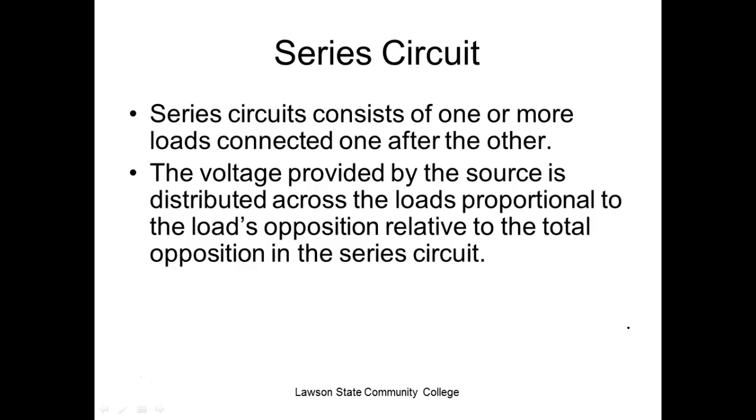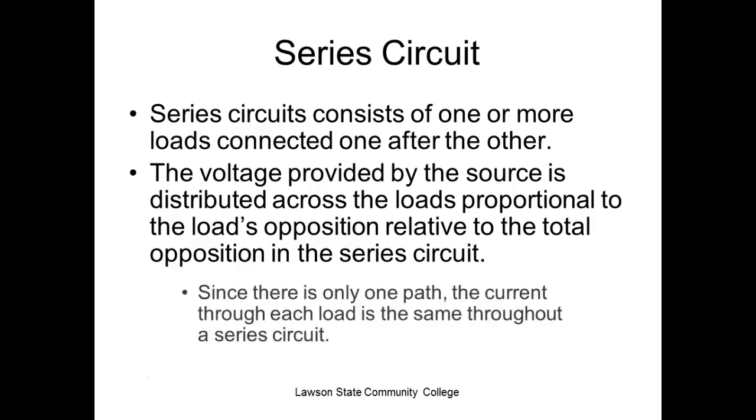The biggest disadvantage we have with the series circuit, of course, is that if we lose one load, with one load open, the whole circuit is going to go. That would be awful. Think about your house. You have a light bulb blow out and your whole house goes out. We use it a lot in electronics, and you see series circuits when you put up your Christmas lights. But they're not series anymore. Some of them still are. Now most of them are series parallel. So if you lose one bulb, you might lose 12 lights, but you still have the other strings, right? So your Christmas tree doesn't go totally dark.